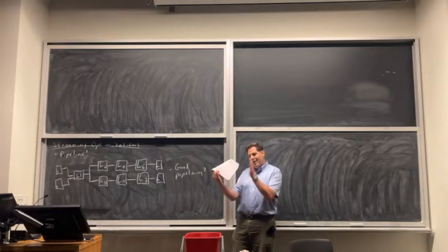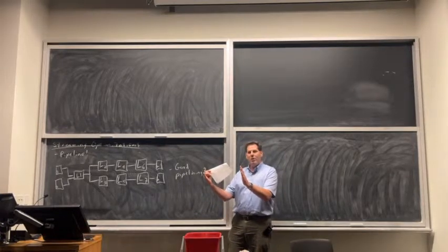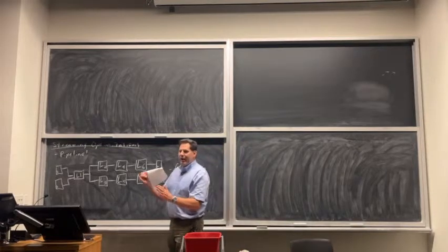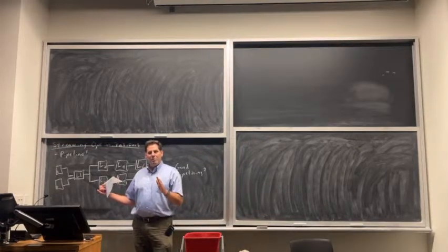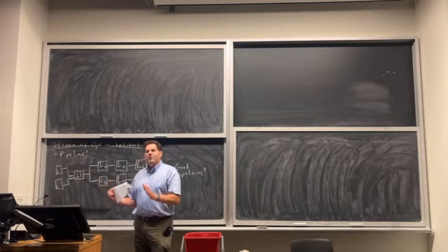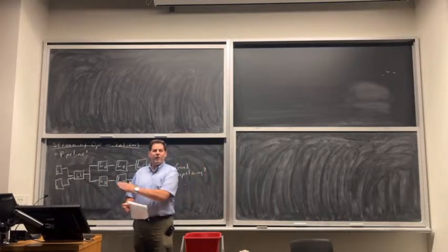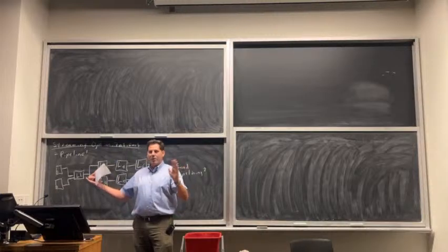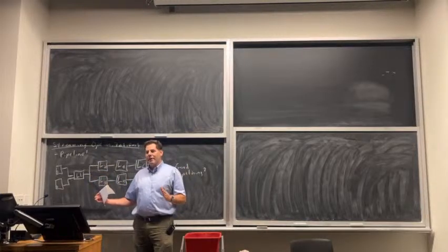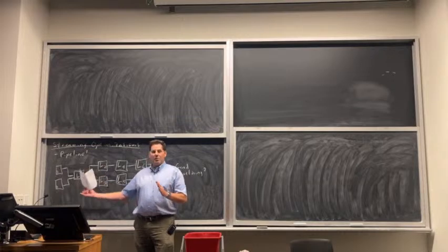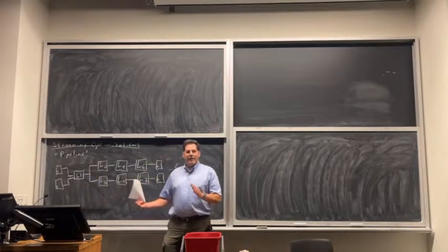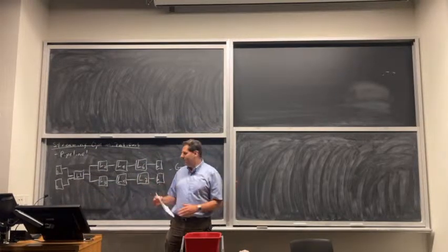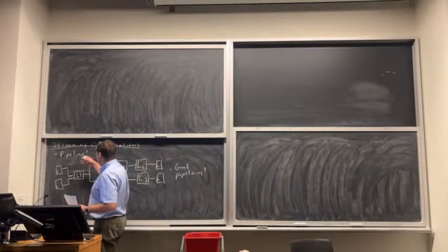If from this point to this point, your inputs are valid, all the intermediate points will be valid and will never need to stall, then you can just use regular registers with no back pressure. And then at the boundaries, if maybe my inputs at this point won't be ready, or I might not be able to produce an output for a while, then you could use back pressure and FIFOs. So you could combine them. Okay, so let's talk about streaming optimization.